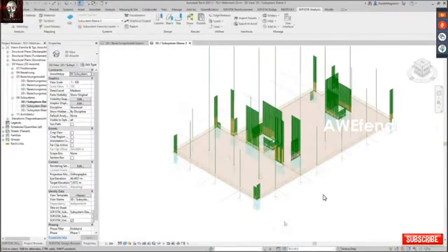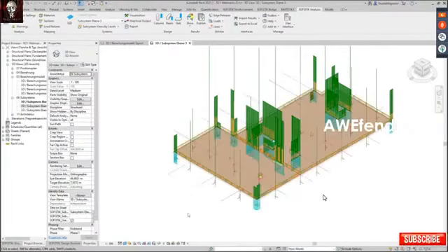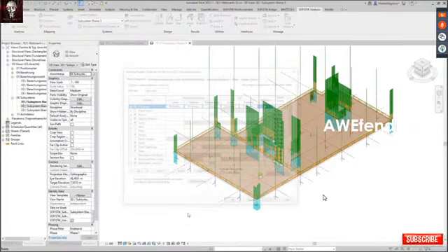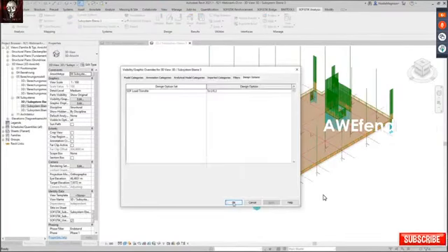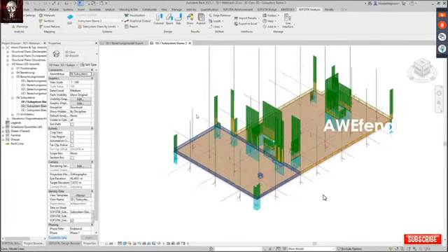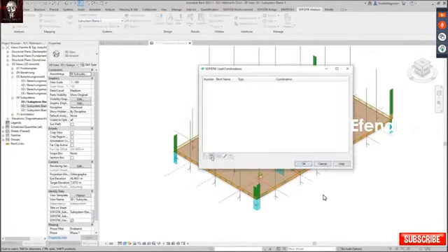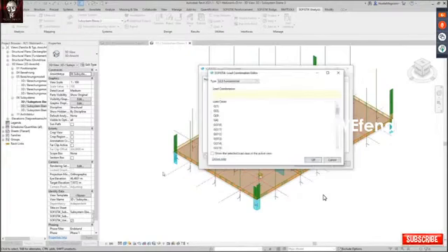So generating the loads from subsystem here, level 4, which is directly above the active subsystem, activating them in the active Revit view using design options of Revit. And with this, I would have this load transfer also available for my analysis. Now, talking about new features, I would like to show you how to generate global load combination in Revit.